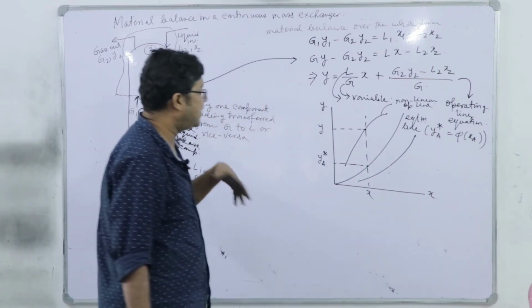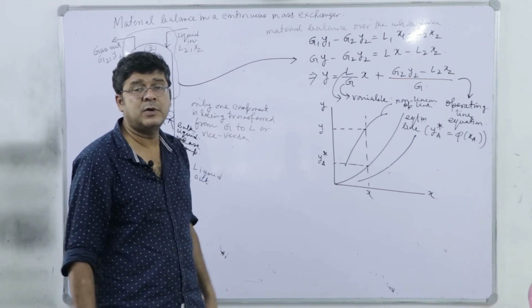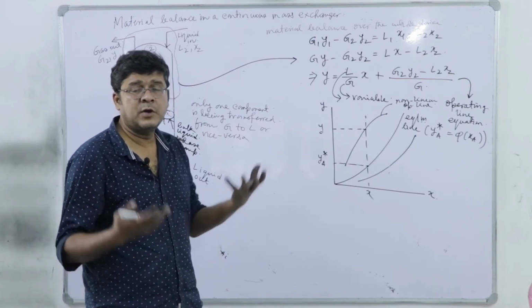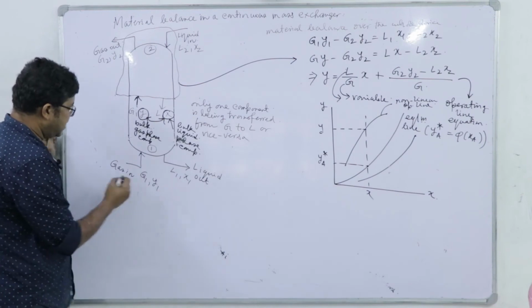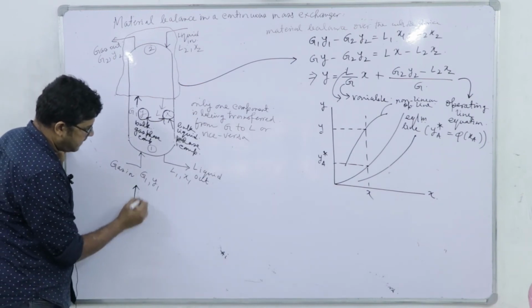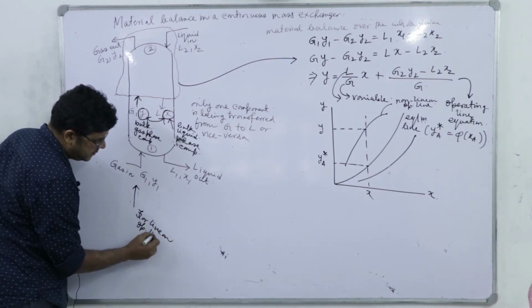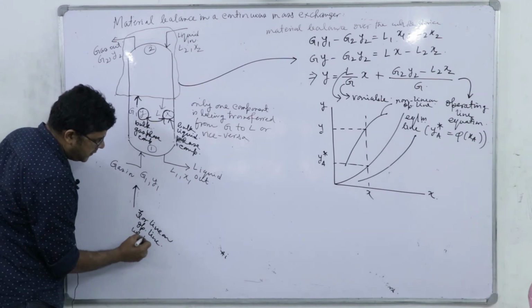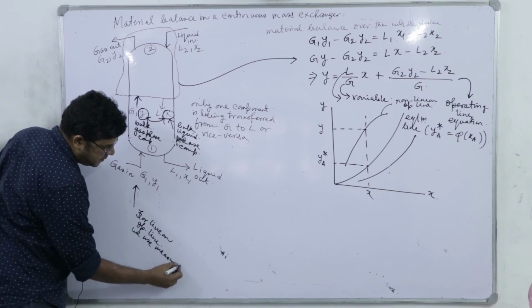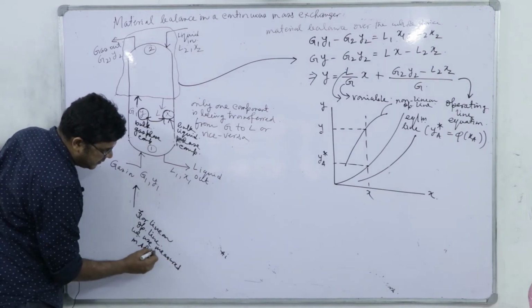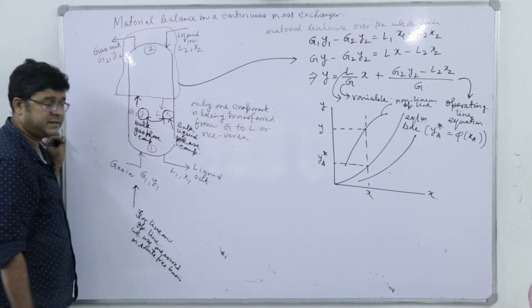So that's the relation between the equilibrium and operating line and the respective tentative measure of the driving force. Now the question exists that if the operating line itself is nonlinear, how to draw it, and whether it is possible to actually change the coordinate system to generate some linear operating line? Yes, it is possible. It's possible if I go for a linear operating line. We use measures in solute free bases. Right, as I mentioned that only one component is being transferred.